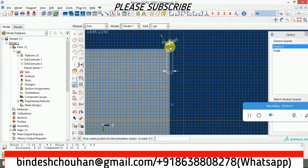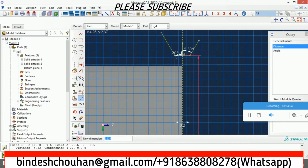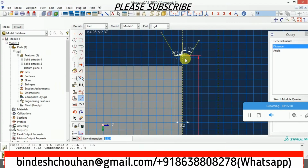Now this distance from the center, from here to here, will be 2 point this. I have calculated it using this formula: d minimum. You can use d major minus 0.82 p.